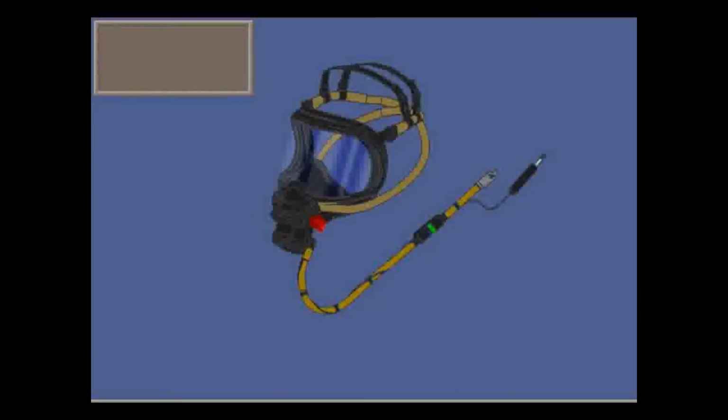The flight crew masks have a dynamic microphone, an inflatable harness, an automatic diluter demand regulator, and an oxygen line with a low flow warning indicator. To put on the mask, press the harness inflation button, which inflates the straps, and put the mask over your face. Releasing the button deflates the straps and they compress. Optional masks have comfort straps where you adjust the tension by slowly releasing the inflation button.